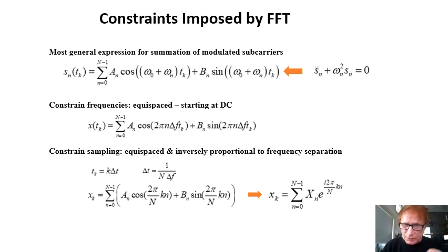The third model leads to the exponential complex form used for the FFT. The FFT math form is a direct result of applying the sample rate constraint to the Fourier series and also applying the Euler equation for the exponential form. The digital sampling interval must be related to the frequency separation as shown in order for the FFT to achieve the n log n processing improvement.